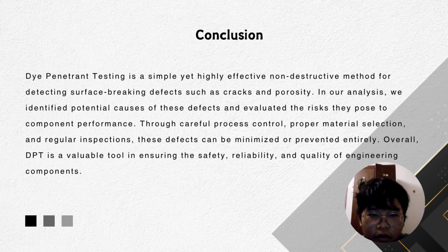Lastly, conclusion. Dye penetrant testing is a simple yet highly effective non-destructive method for detecting surface breaking defects such as cracks and porosity. In our analysis, we identified potential causes of these defects and evaluated the risk they pose to component performance.